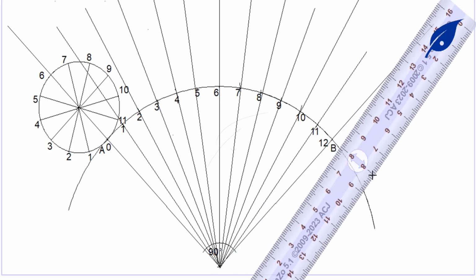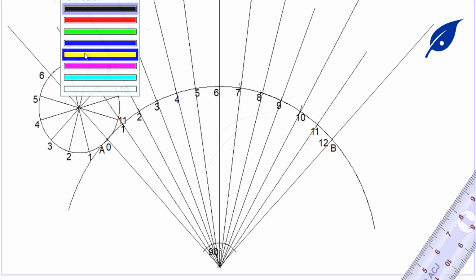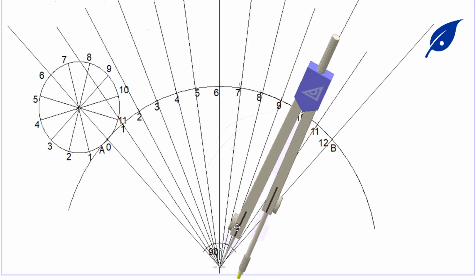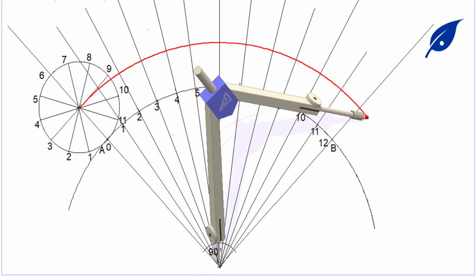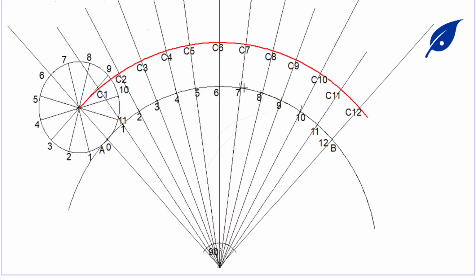Now we've gotten all the 12 points, and remember they are extended out of the base circle. Now we have various points. The next thing we are going to do is to get the path of the center of our rolling circle. For emphasis, I make it red, but for your own work you can make it much darker so that you can get the actual path. It might be similar to the path for 3 and 9, which is why we need to emphasize this.